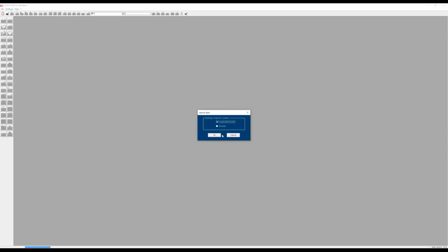Now we have two types of plans, and in addition there are two types or two extensions of the program DCSECTION. There is DCSECTION Lite and DCSECTION Full version. The Lite version only supports longitudinal section to be created manually and without filling of the soil layers between the bore profiles. And the full version supports in addition a site plan and automatic creation of sections from the site plan, which I will show a little later.